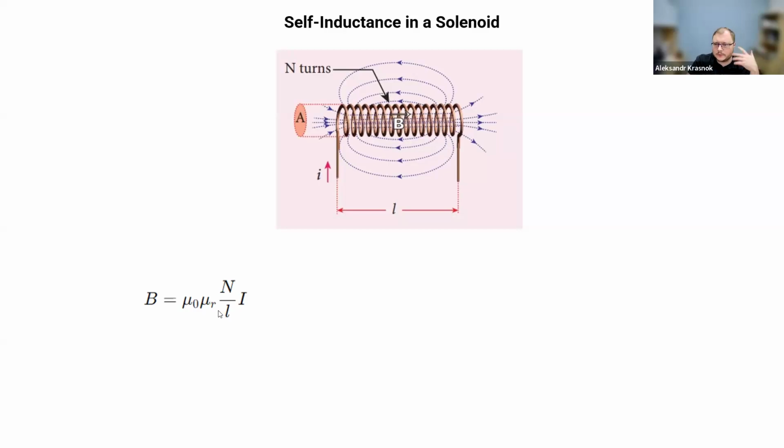The larger the current, the larger the magnetic field, which makes sense. And also the number of turns: the more turns, the stronger the magnetic field. It is also proportional, by the way, to the magnetic permeability. So if you use a diamagnetic, this magnetic field will be reduced, but if you use a ferromagnetic, this B field can be increased by many times, hundreds, maybe thousands.